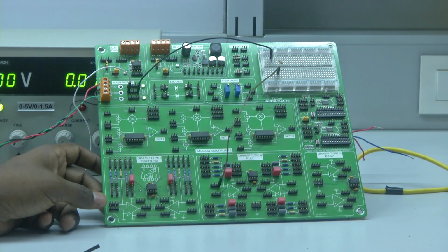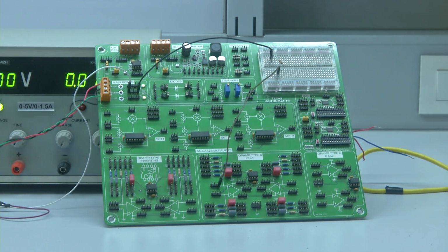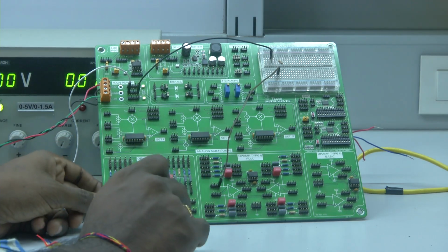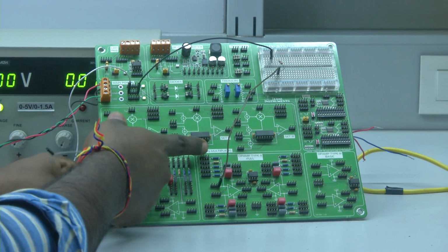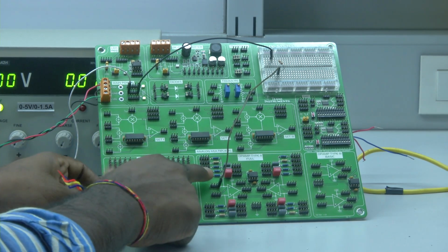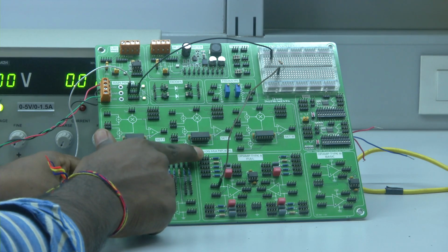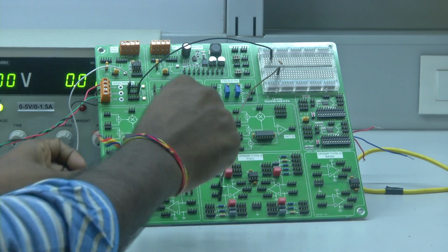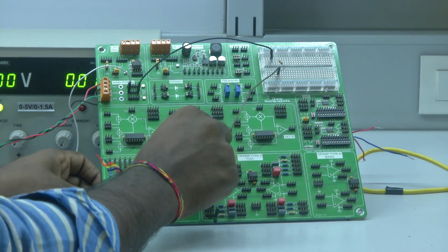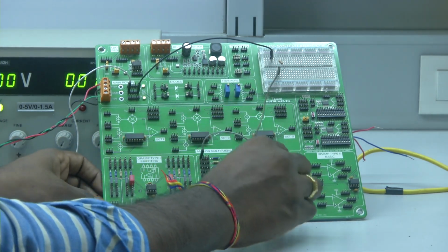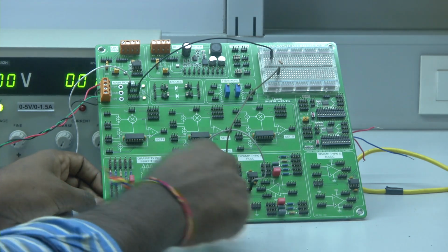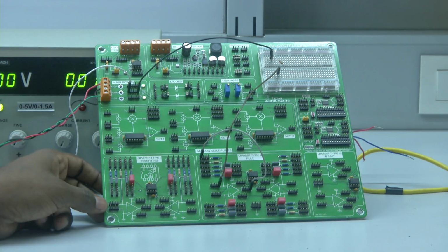Next, what is the feedback resistance? In order to connect a feedback resistance, if you remember, we require a feedback resistance of 1.08 kilo ohm. The closest resistor which is available is 1 kilo, and that 1 kilo is already here. If I consider the top 1 kilo, you can see that one terminal is already connected to the negative terminal, whereas the other end of the resistor I will connect to the output terminal, which means that the feedback resistance is also connected.